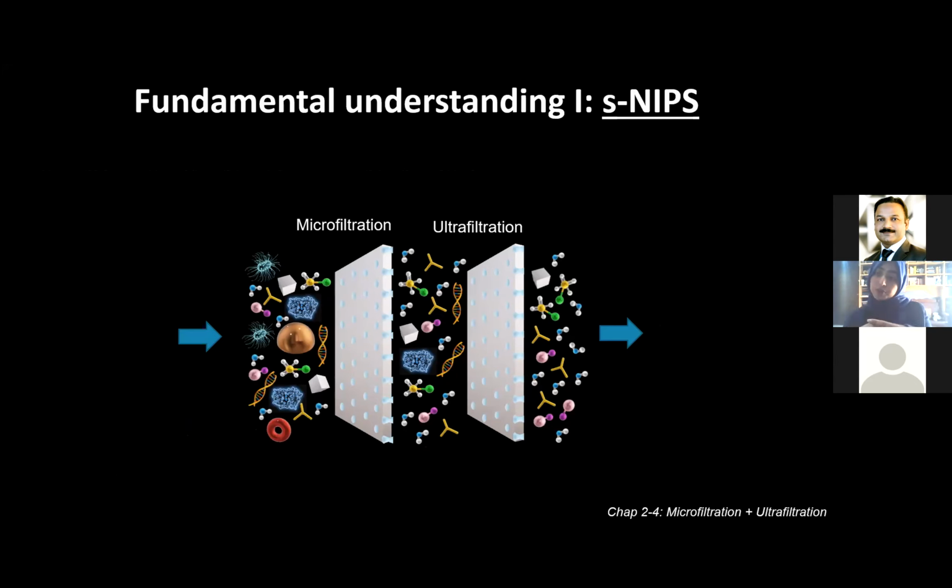The initial trial experiments showed there will always be a need for a minimum viscosity of the solution, which, as you might have an idea, could be adjusted by changing the polymer concentration. So a threshold minimum viscosity is needed, because at lower viscosity the patterns will just relapse very quickly, even before the non-solvent spraying can solidify the patterns. Therefore, with the optimum viscosity, we could create the patterns.